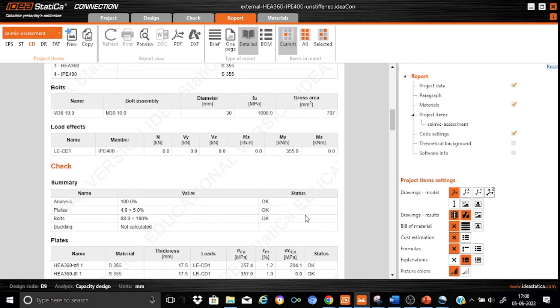And normally what I do is that whenever I have this kind of a structure which involves a semi-rigid partial strength joint, I normally go ahead with two ways of structural analysis. I perform either a static pushover analysis, and that will let me know whether the joints will be capable of taking the structure to the desired deformation levels with the capacity well in place, that is without any capacity degradation.